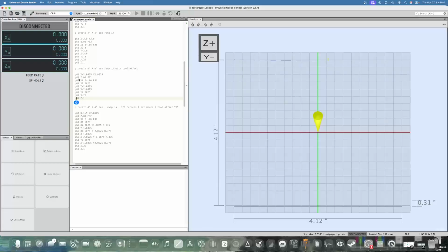The reason for that is once you exceed 90 degrees, like you do 165 or 250, or the full 360 degrees, it's possible to have more than one calculation. While it fits the way you want, it can also mathematically fit a different way you don't want. And as soon as it realizes there's not a definite answer, GRBL again will get lost and just mow your part down. So 90 degrees max, you can do less, but 90 degrees max is ideal, and IJK.